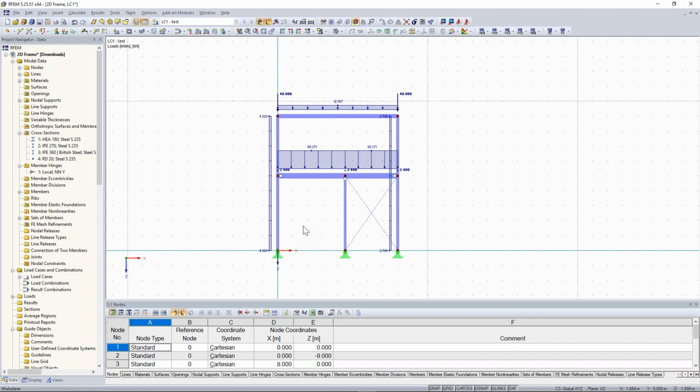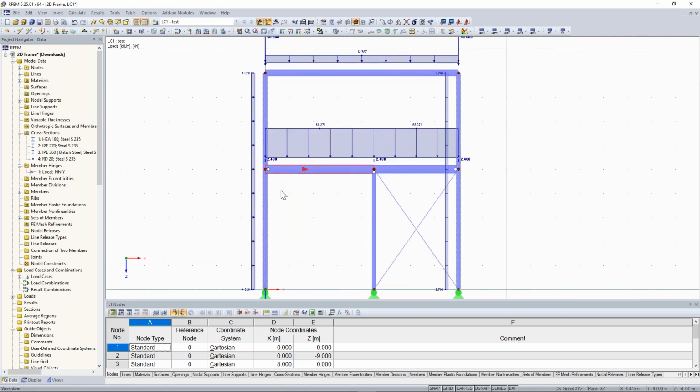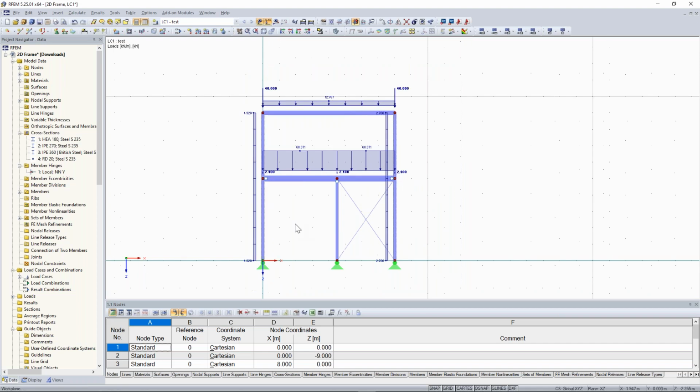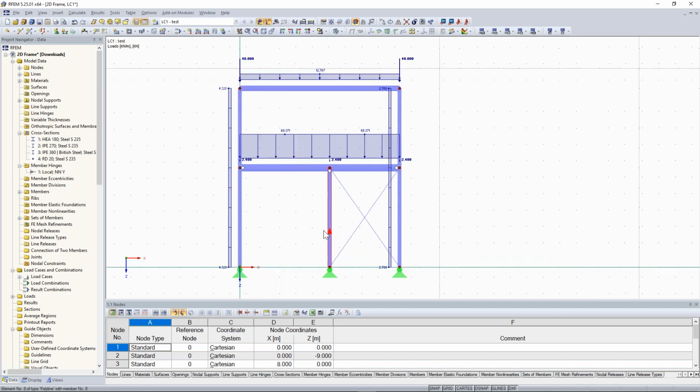Should we assign beam model type for all frame? Well, that depends, right? Exactly. So it's up to you how you define your structure. You can do it and then assign the member hinges, for example. If you want to have here a hinged connection, then you can add the hinges. And here, for example, for the bracing, I defined the bracing because I want to have this as an additional stability factor. So I added here also the bracing. I hope the question was answered.